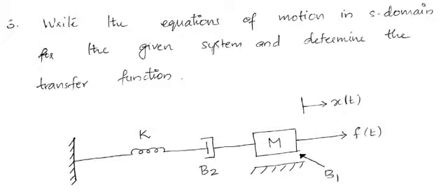Okay. So basically our first step is to identify the nodes. Nodes are the meeting point of elements. So if you look here, you can see we have a spring with the stiffness K and a dashpot with frictional coefficient B2 connected in series, right? So the meeting point of these two elements is a node, but in that particular node we don't have a mass element, right?